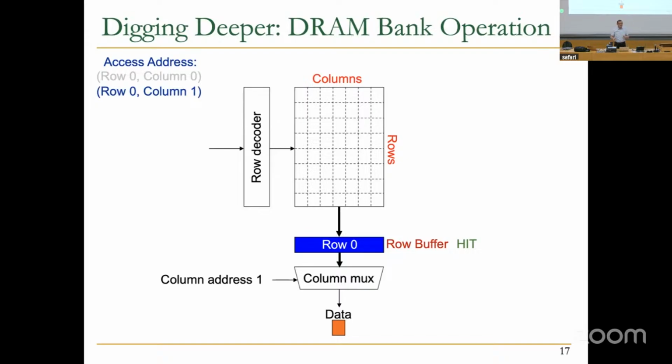So this is an example of caching. We're going to introduce the notion of caching. Basically, we accessed a lot of data initially, concurrently, and then we put it inside the row buffer, which is an example of a cache, which is essentially a circuit that memorizes or remembers the data. And then if we want to access the same row again, the access is much faster because it's already there in the cache or row buffer.